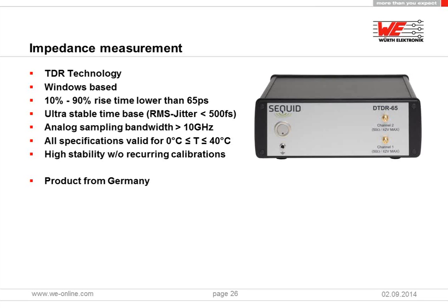So now, as we already mentioned, we come to the summary. Signal integrity with flex rigid. We have seen that flex rigid technology itself has some system advantages, but at the same time there are some stack-up constraints which require special actions in design and layout.